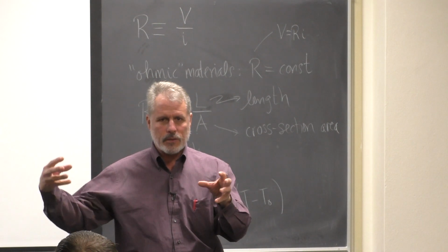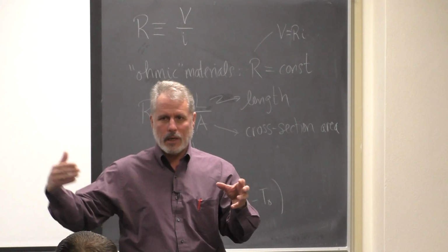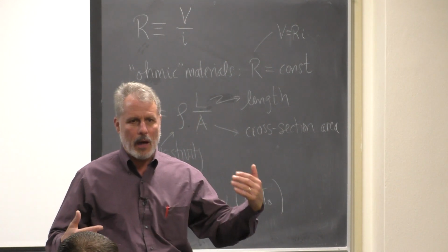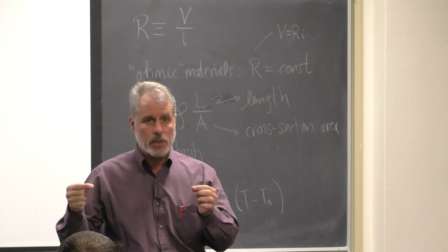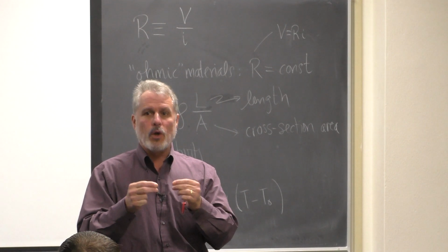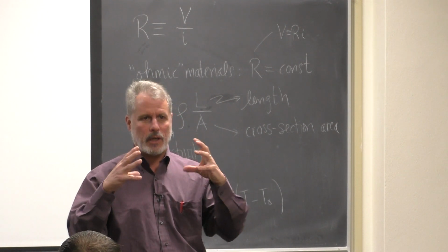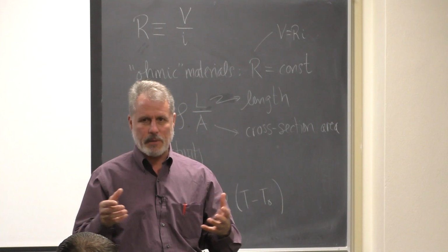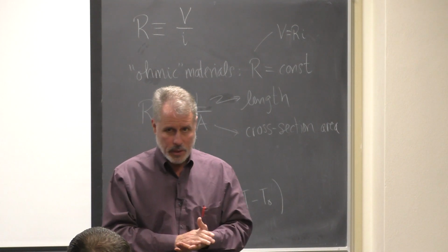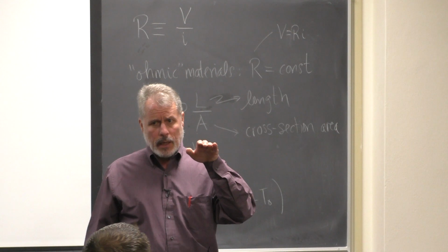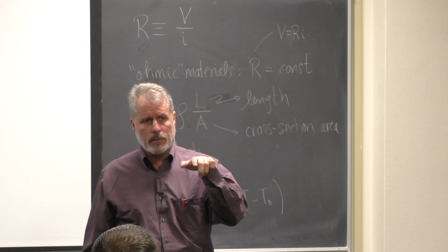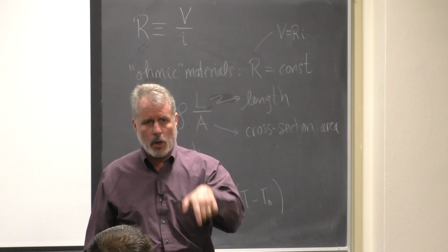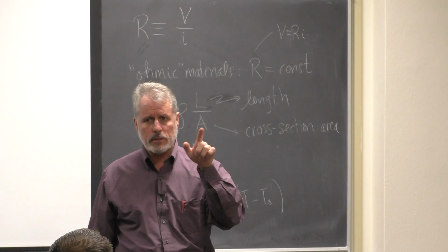So the electrons that are moving about due to the presence of an external voltage are going to be finding more collision spots. The cross-sectional area of collision increases by having the temperature increase. So in a conductor, the resistance goes up as a function of increasing temperature.